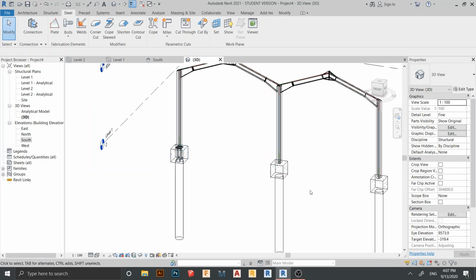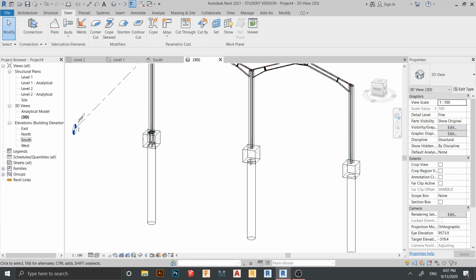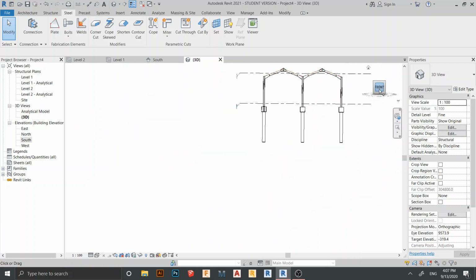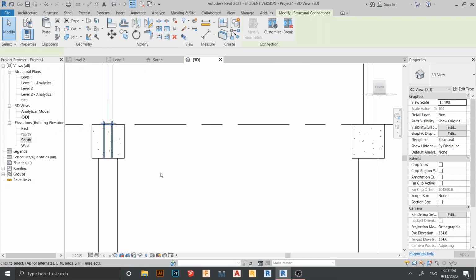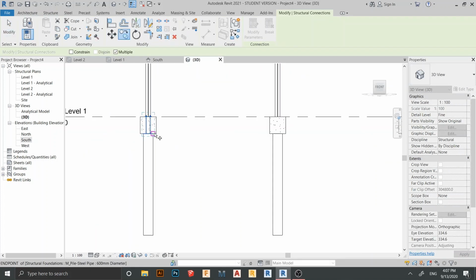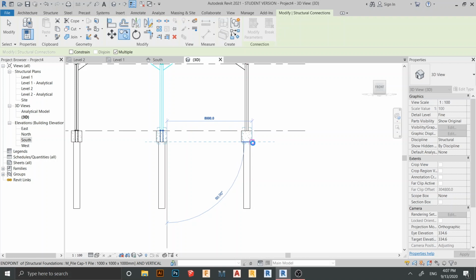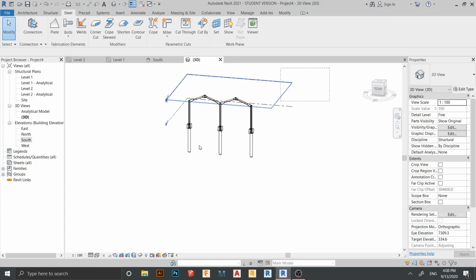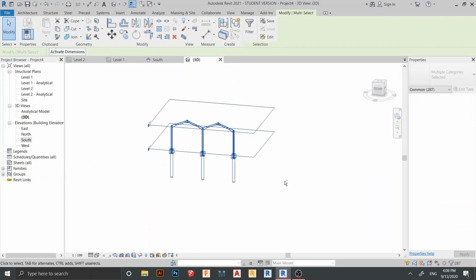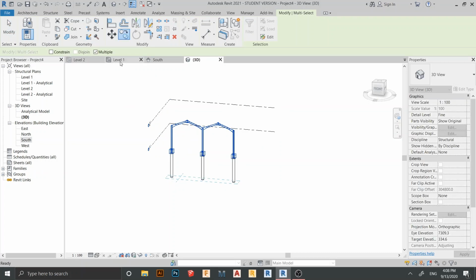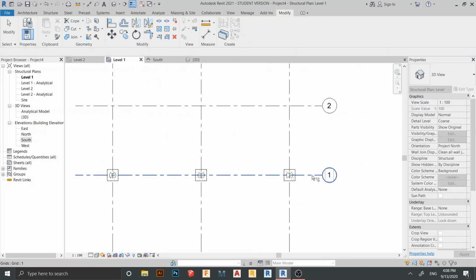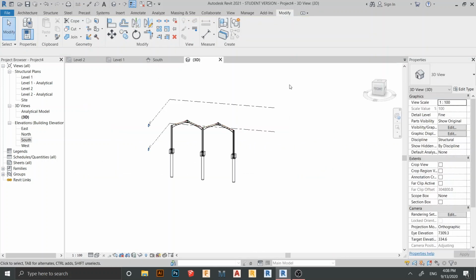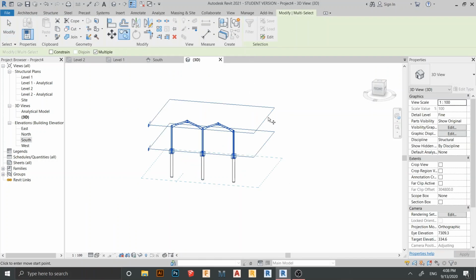We need to copy our steel plate to another two girders. After that, only we start copy for all our structure. I just select here one like this, CO for copy, shortcut key, start from this corner here until here and until another one here. Hit escape a couple times, go to my 3D here, so I select all like this, then shift key on my keyboard to unpin these two levels here and go to copy, start to level 1 and I start to, okay, I think go wrong, go to our 3D again, select all like this, copy, okay, sorry,